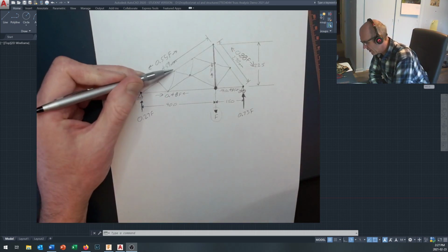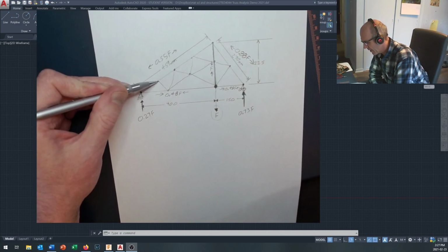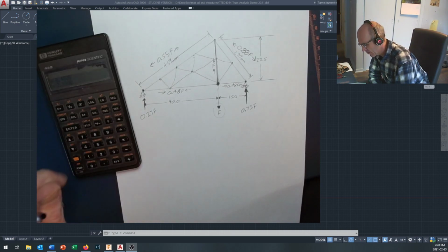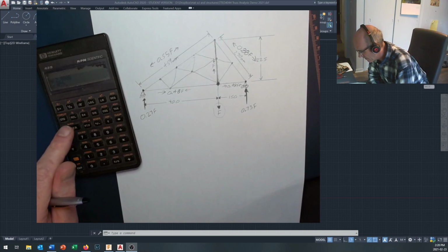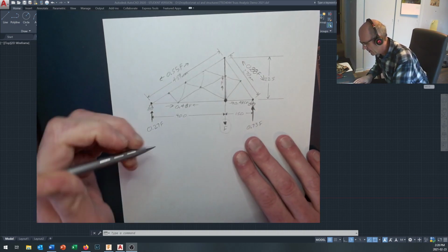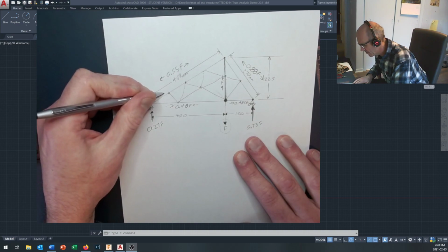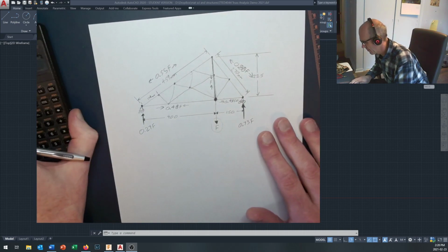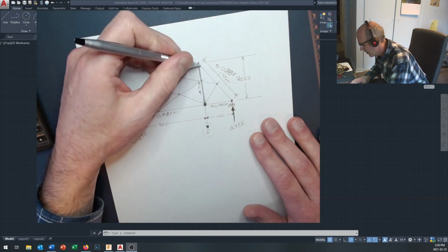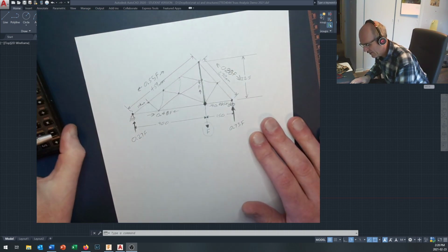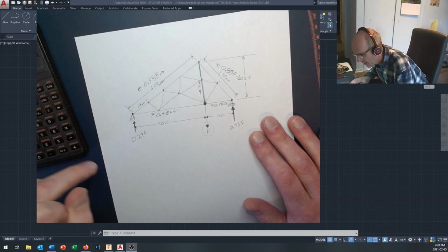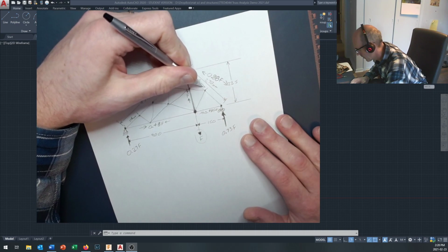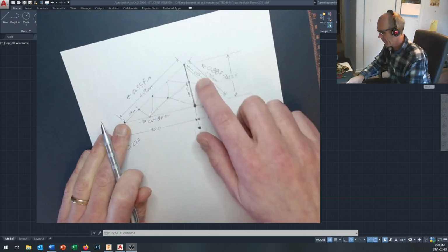Now, one of the things that I did do here, because I broke this side down into 4 sections right here, each of these chunks is going to be 459 divided by 4. Each of these chunks is going to be 114 millimeters long. Whether they should be evenly spaced or not is something I'm going to ask the computer to give me an idea about. And over here, it's going to be 270 divided by 2, which is going to be 135 long for that member right there.